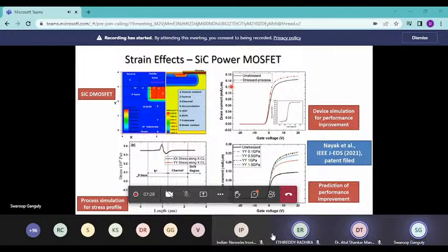See, this is one point maybe I should take a minute to tell you: a lot of semiconductor device physics actually transfers across applications. If you are improving mobility in the logic CMOS device, which was the original motivation behind strain engineering, it will also improve the gm, the transconductance of the device, and make it a better, higher gain analog device.